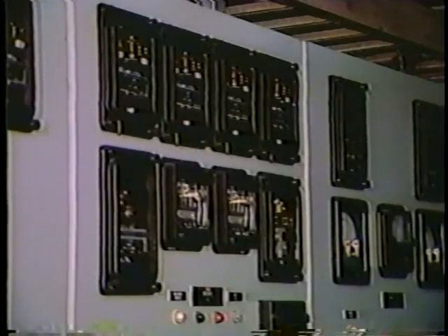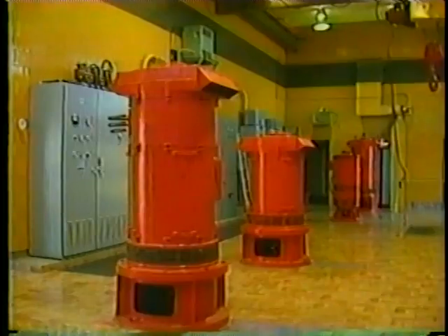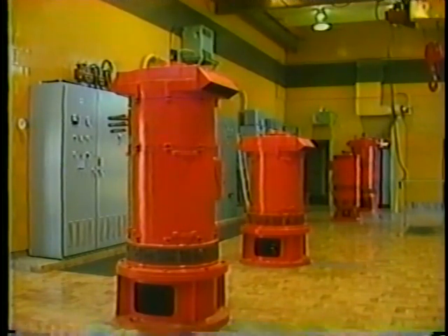Overcurrent relays are widely used throughout the power system, not only for feeder protection, but also for motors in industrial applications and for backup protection in other areas. When applying time-over-current relays of the electromechanical type, 2 points that must be considered are over-travel and reset time.